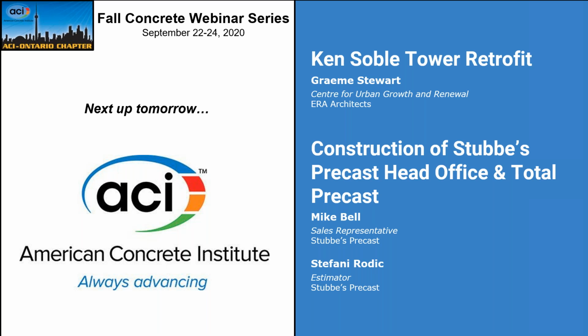The other thing, on a production basis, we had issues where the source of the materials varied, and so we had to ensure that we got consistent results from the source. That's of the coarse aggregate. The other thing we had is with the batching of the concrete. There were batching problems where we were getting variations in the amount of sand versus stone in our mix, and it was due to the way they handle the materials, the way they distribute the materials up the conveyor belt, the way they put them in from the stacker into the various bins.